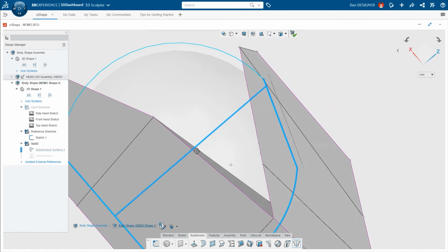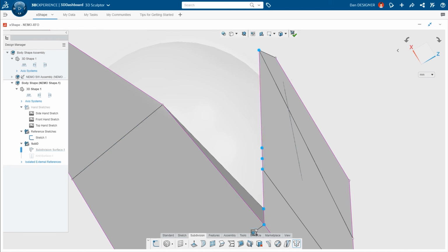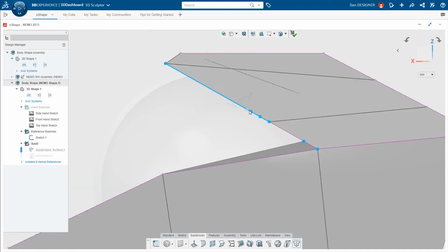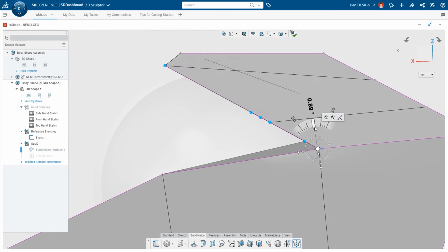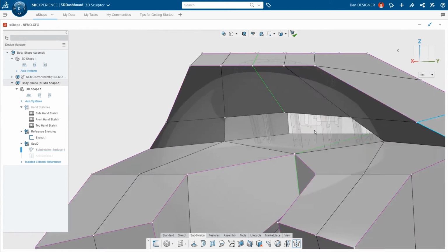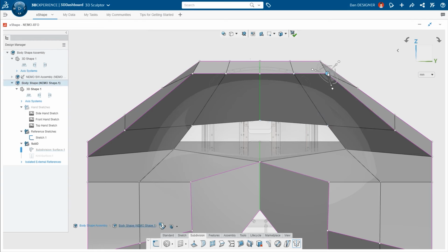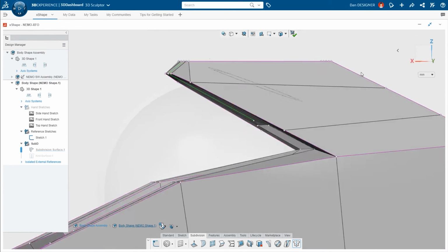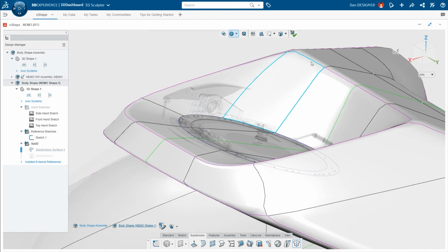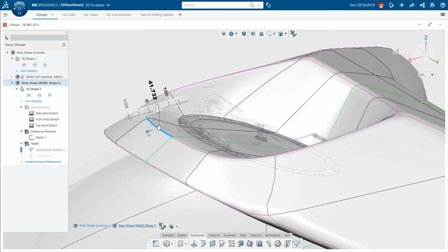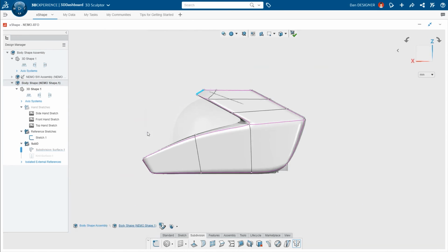To hone in the angle of the front faces, Dan can select the entities and reposition the robot to the pivot point. If this was a face that required a specific draft angle, Dan could snap to the on-screen protractor to dial it in perfectly. To leave the coincident faces undisturbed, Dan can once again reposition the robot accordingly. Dragging the webbing of the robot will ensure his translations maintain the coplanar alignment of the faces. After a few more adjustments to the hood, Dan is ready to tackle the pathways on the side of the design for the thrusters.